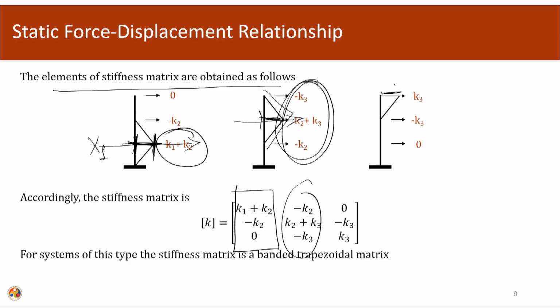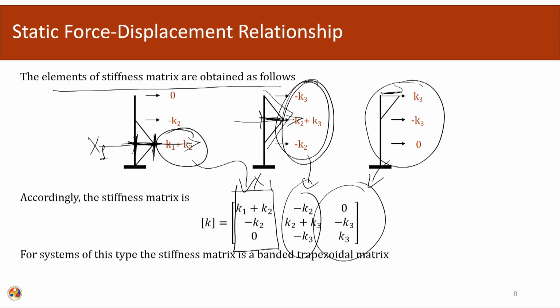And similarly here we give a unit displacement at K3 and the amount of force required to cause this again becomes my column matrix. So, we arrange the column matrix by giving unit displacements at the chosen degrees of freedom. These 3 degrees of freedom we rearrange, and if we measure the forces associated with them to cause these displaced shapes, it becomes the stiffness matrix. So, this is the simplest way we can calculate our stiffness matrix.